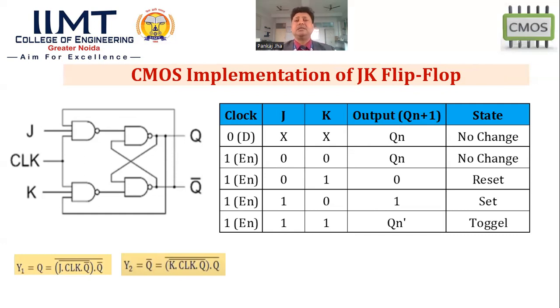In that case, the circuit produces an invalid output. So JK flip-flop removes that problem. The first important thing about JK is that the 1-1 condition, which is problematic in SR latch or SR flip-flop, is removed by JK flip-flop. That's why we are using JK flip-flop for more precise designing.